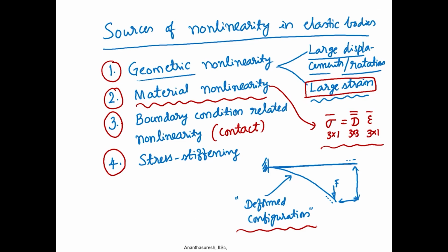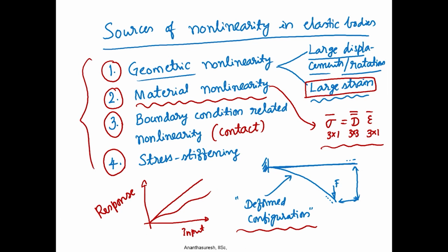But in general, nonlinearity really means that whatever response you are interested in, let us say there is some input, usually a force or displacement, and some response of the compliant mechanism. When that is not linear, and is nonlinear in some fashion, we call it nonlinear response. That can be due to any of these sources, but only material nonlinearity we discount in the case of compliant mechanisms.